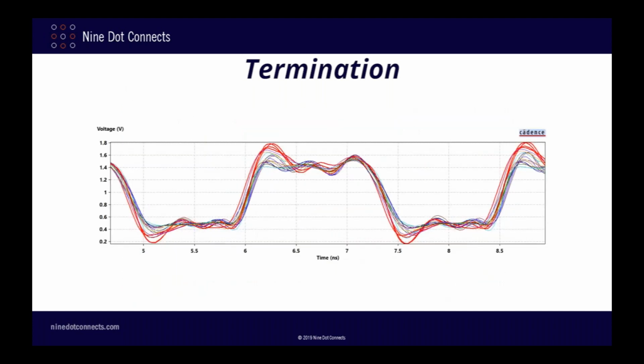As an aside, I'd like to mention that I could probably have tweaked the resistor values and improved the signal integrity if I really wanted to. This kind of termination tuning is pretty common in high-speed designs, but is usually only done once the board is fabricated. Since it's just a simple matter of changing resistor values, it's not a very expensive change to the design, and can even often help with EMI and other issues.